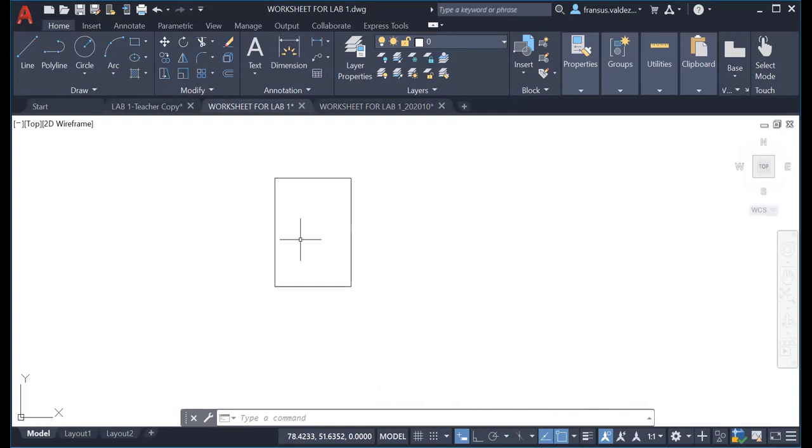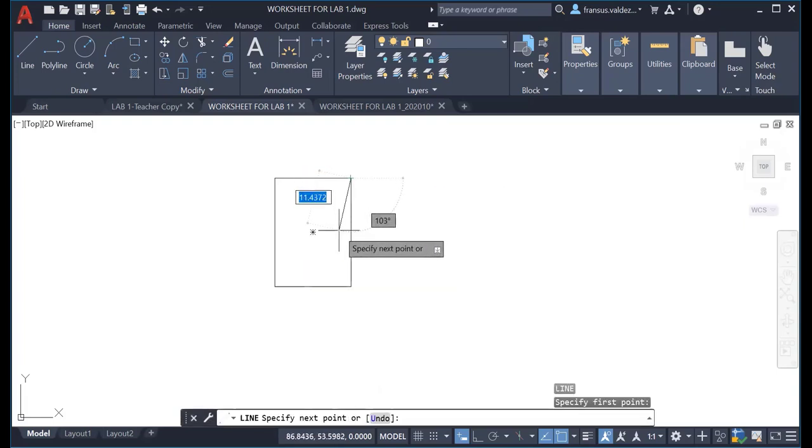Now in the existing building, in the drawing, you will notice that from this portion here, it is 8 meters below, and then to the left, from 8 meters to the left is 6 meters. So let's establish first the reference point. So line. So the first command is we just make a line. So L or LIN, or L for the shortcut, line from here up to this one is 8 meters. However, you see this is not straight. So if we want this one to be straight so that there are no crooked lines, we click F8.